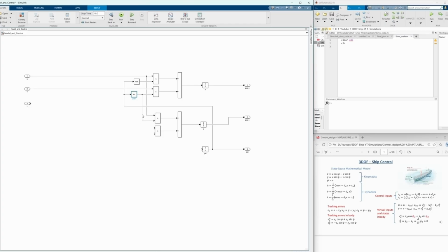Okay, so one tip I will give you is that you should always write these signal names over here. You will find out now why I'm doing this. Because I have psi over here, when these connections are complex and there are many connections, it is difficult to follow. So I can simply double click over here. You see psi appeared automatically.